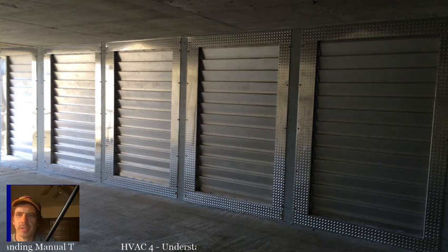VAVs with electric heaters in commercial buildings. For whatever reason, sometimes the fan is not powerful enough on its own to handle the heater kit that was installed. The heater kit is oversized for the airflow that blower can put out. So you will often have to adjust them. You'll have to adjust the primary air damper in the VAV from the rooftop unit to provide some extra airflow to keep the electric heaters from cycling on and off, especially the second stage.